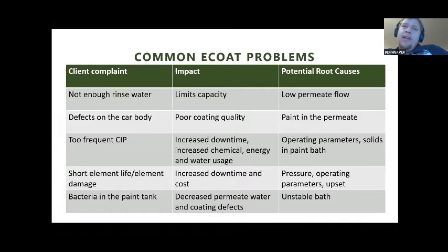Another thing we hear is that we really want 2 years of membrane life, but we're only getting 9 months. The impact of that is increased downtime, whether from cleaning too frequently or replacing elements more frequently than we want to, and it's increased costs. One of the ways we look at it is: are we operating at the right pressure?